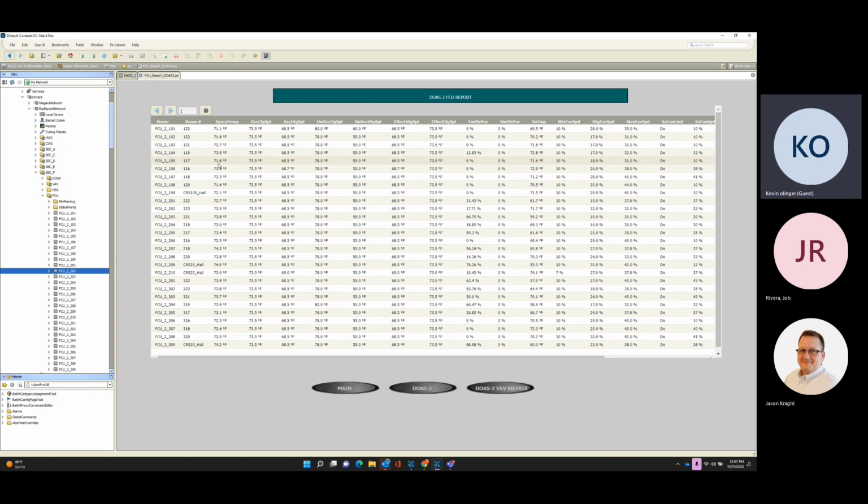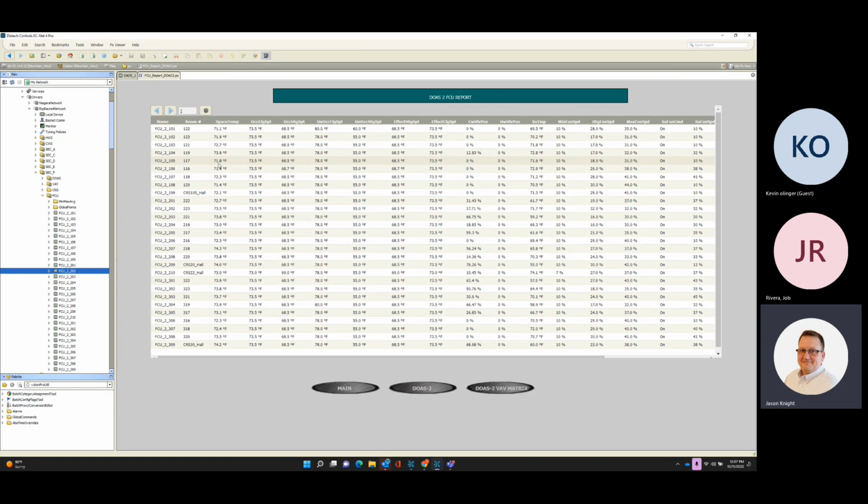I guess what percentage is the chiller and boiler gonna fire off to? Is it a 20%? Oh no, they're gonna go all 100%? No, they'll stage up based on the leaving chill water set point or leaving hot water set point. So let's say the chill water set point is 55 degrees. And when the chill water system gets activated, the chillers will stage accordingly to get down to 55, and then they'll back off. And then as the outside air temp increases or decreases, that set point is automatically adjusted to go down to like 44 degrees. So if it's 80 degrees outside, you're going to have a 44-degree chill water set point.